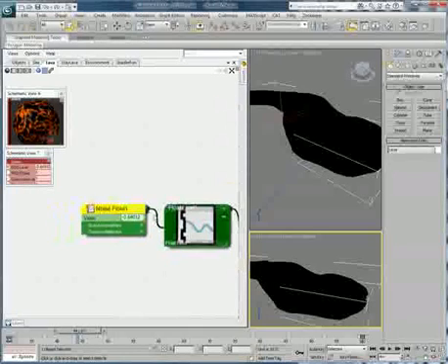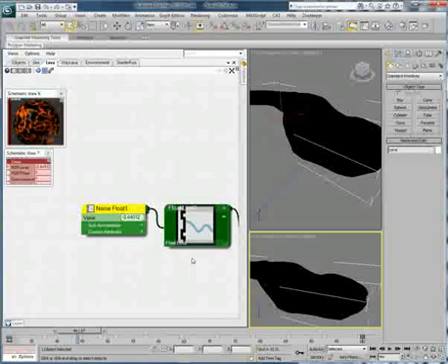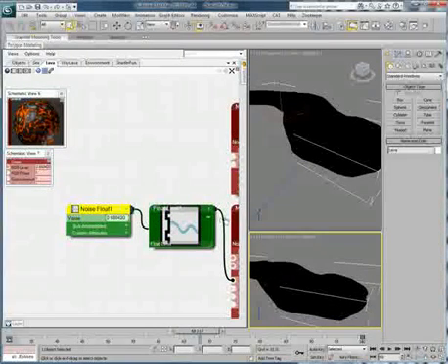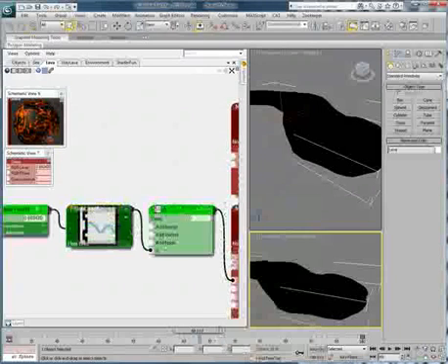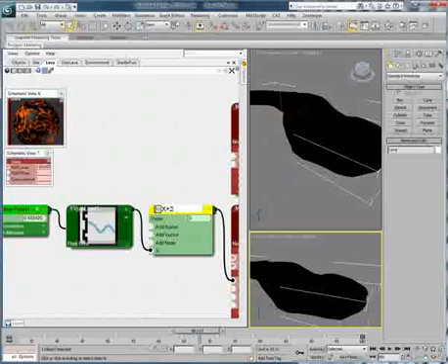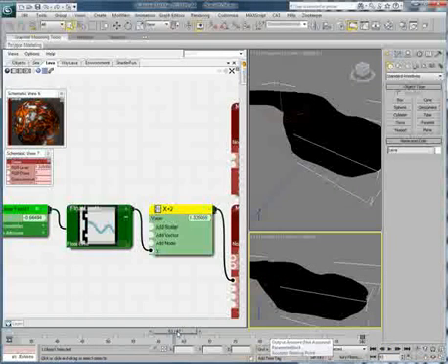And possibly at some point I may want to take this and put some sort of expression in here. So even though this is maybe plus or minus 10, if that map isn't really getting the amount we want, or we need it to be more, I can insert another in here. So I'm just going to insert an expression, and here's my expression. You can see it pipes right into X. And if I needed to adjust this easily, I just double click here and type, X plus 2. Okay, and you can see the update there, and as I play back, I can see these values and the value at the end of the string and what's going on there. And I can also see the updates in my preview window there, which is really pretty helpful.